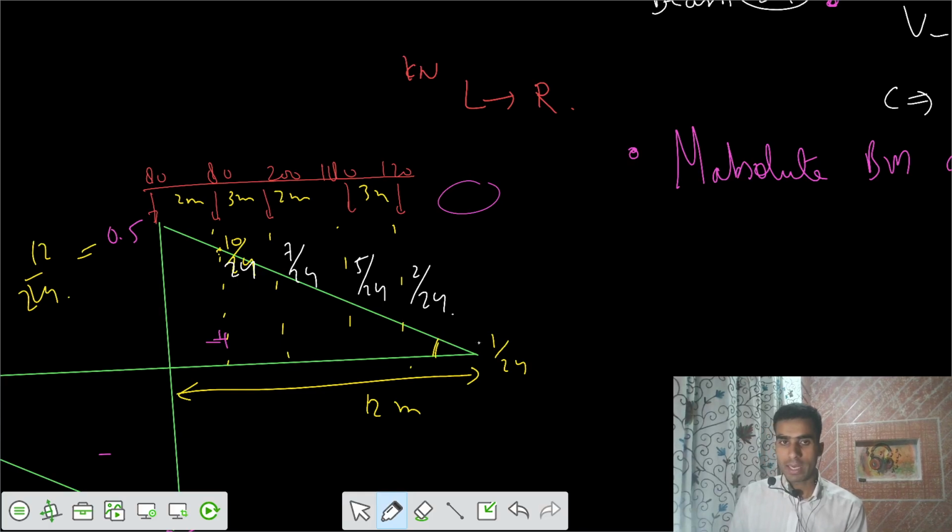And we can directly now calculate the V value. Let's calculate it as V1 positive, because these 80 kilonewton loads are smaller as compared to 200 and 180. So then we can do one more iteration for this one.